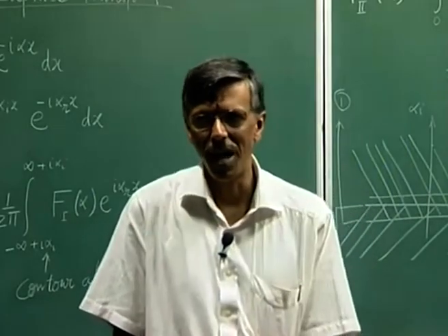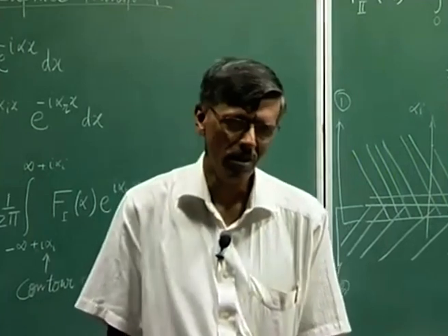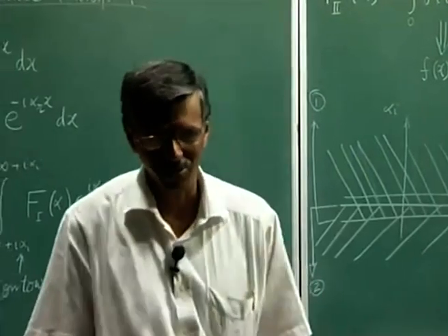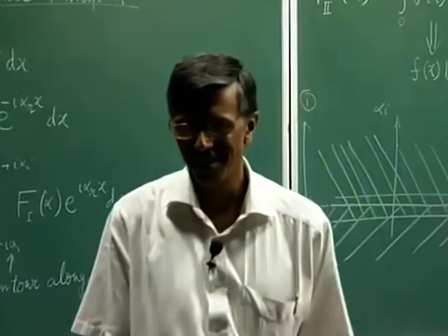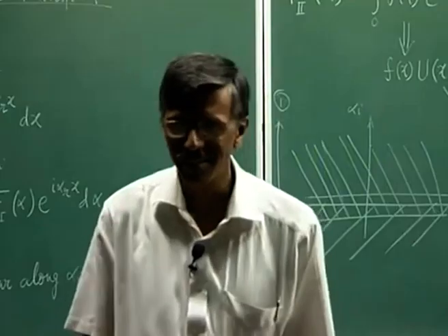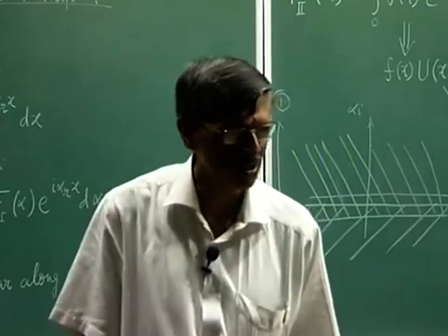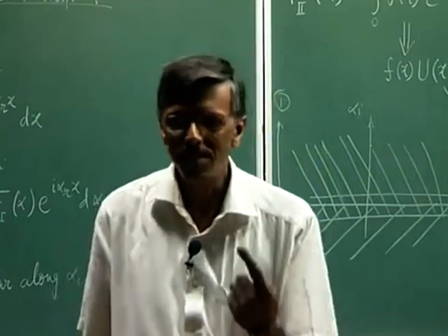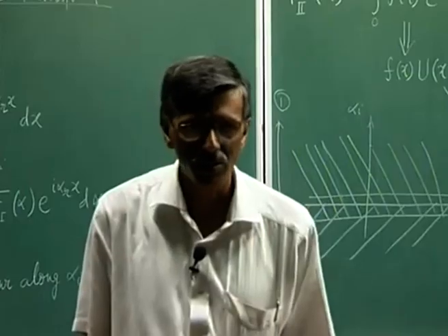Unfortunately, instability studies would not distinguish these cases, because you are looking at the same Reynolds number, same tunnel, everything the same. When we produced this result, it was quite unnerving, especially for people who had just come out of the first course in fluid mechanics, where they have been told time and again about the importance of similarity parameters. And here we are saying, well, that is not so. What it actually means is that there may not be a single similarity parameter that one should be looking at.